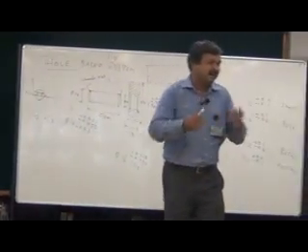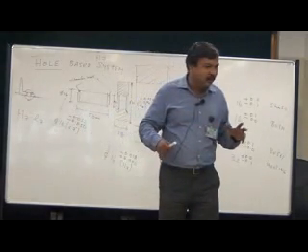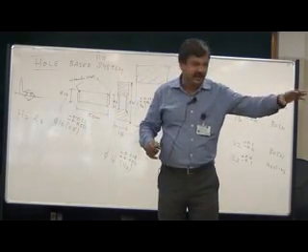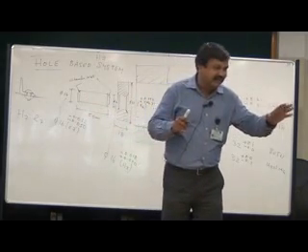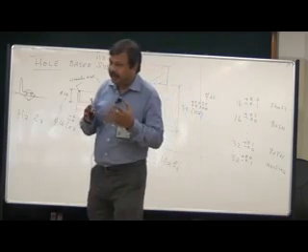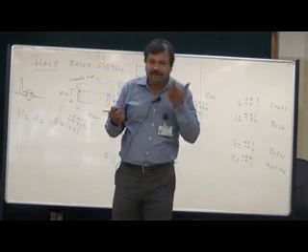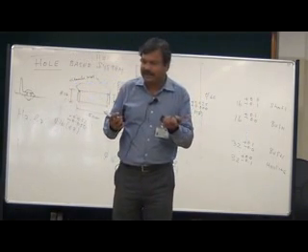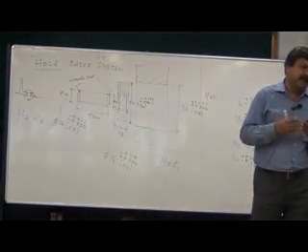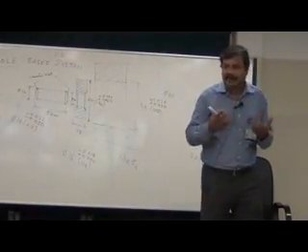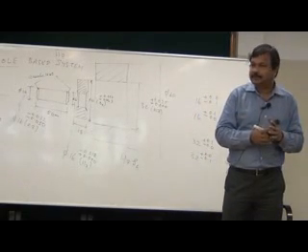They mix clay with sand and then they make it to the required shapes. They dry it. After that, what do they do? They put it in a furnace called the kiln and then they heat it. In the furnace, the temperature is raised to a certain temperature and then a very strong ceramic formation takes place. You get a brick. Brick is essentially a ceramic. The bond between the granules is strengthened and thereby you get a ceramic.